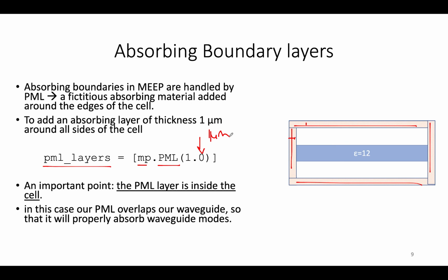An important point to take into account when designing a simulation for MEEP is that the PML layer is inside the cell that is our simulation domain. In this case, our PML overlaps with our waveguide. So we'll probably absorb waveguide modes exiting the boundary.